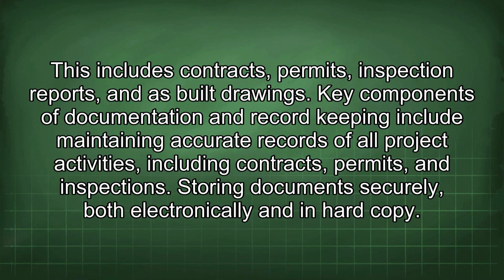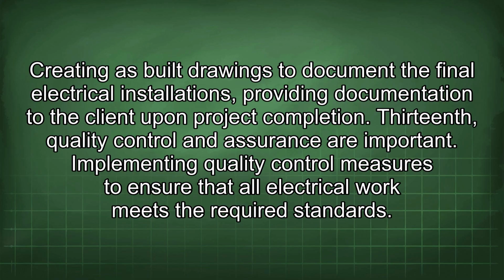Key components of documentation and record keeping include maintaining accurate records of all project activities, including contracts, permits, and inspections. Storing documents securely both electronically and in hard copy. Creating as-built drawings to document the final electrical installations, providing documentation to the client upon project completion.